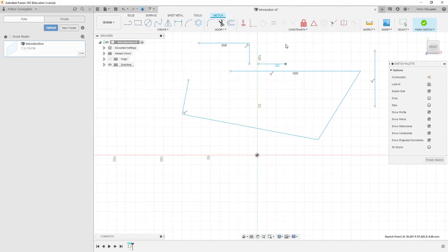So depending on the angle of your piece, if it's like there, it'll go horizontal. But say we have it here and we want it to be horizontal or vertical, clicking it to do one will make it vertical, but if it is below that angle, it'll go horizontal. You can make your own opinions whether you like that or not. I'm not too big of a fan. I would rather have one for each. And like the newer versions of SolidWorks, when you make a sealed section, it gives you this profile.